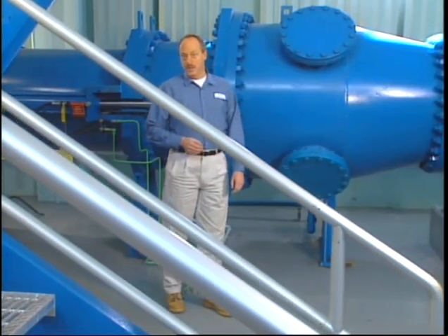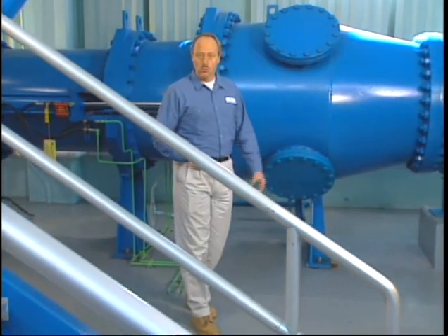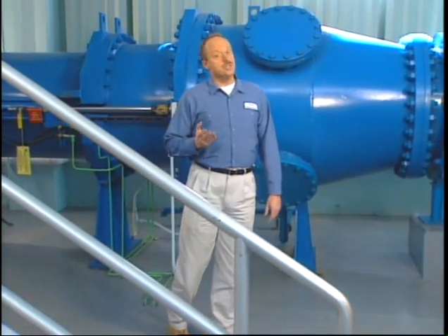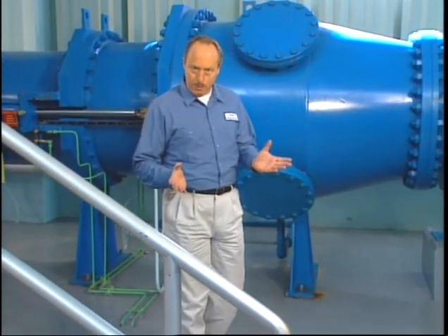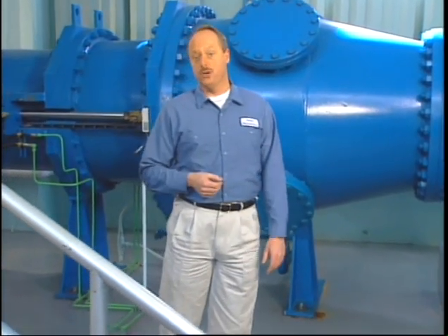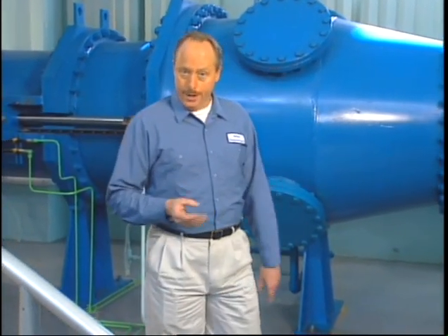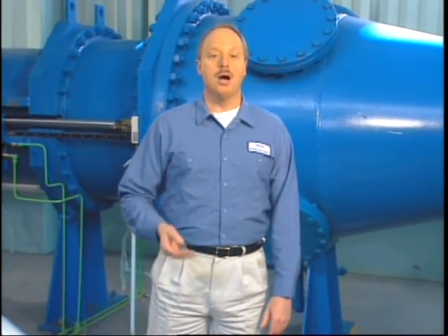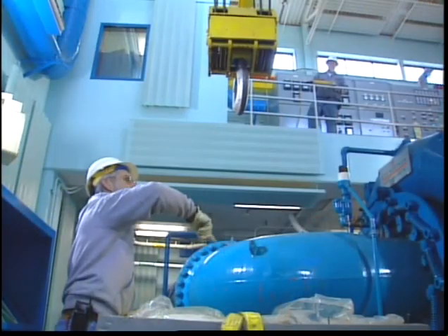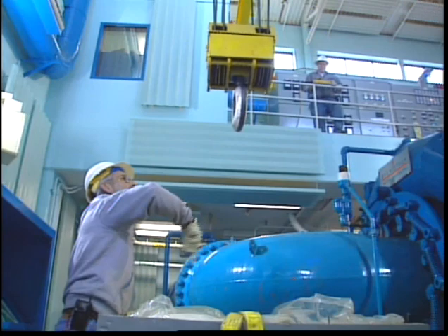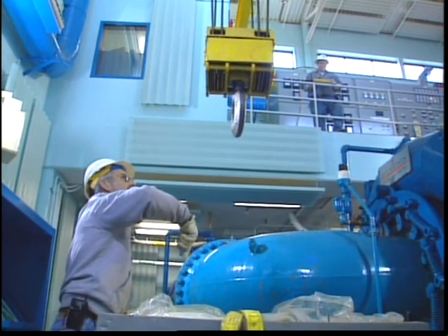Now that the hoist has been inspected, we can go ahead and put it to work. That requires a crew of at least 2 people: one person to operate the crane and one person to signal the operator. Additional riggers may also be needed to help hook up large loads. Center the crane hoist directly over the load so it won't swing when it's first lifted.